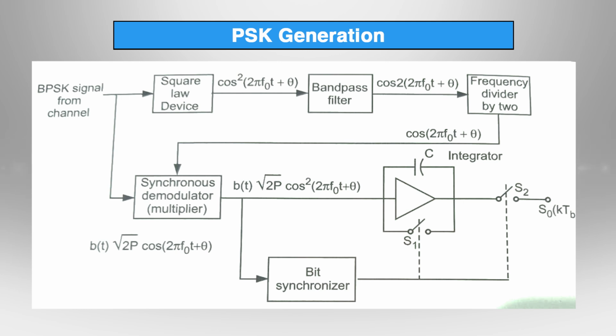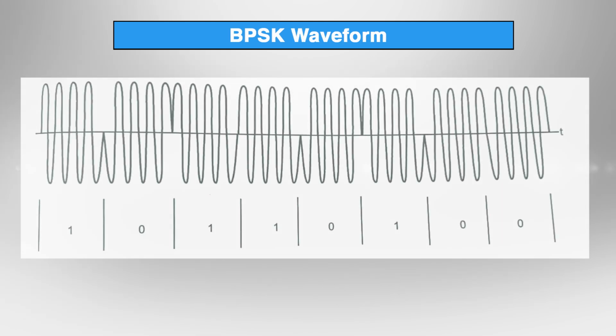Let us reset the integrator voltage, that is, an integral number of cycles are there, and integrate over all those durations, TB1, TB2, TB3, TB4, likewise integrating all the cycles or all the carriers as per the different bits, right. So, the phase change occurs in the carrier only at the 0 crossing. You will find this in slide number 13, figure number 5, you can check over there.